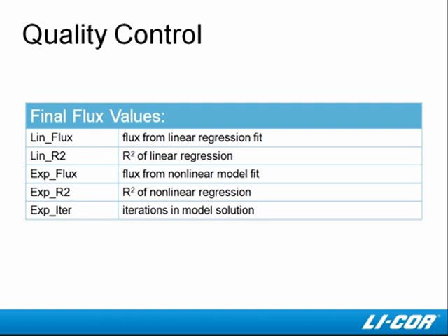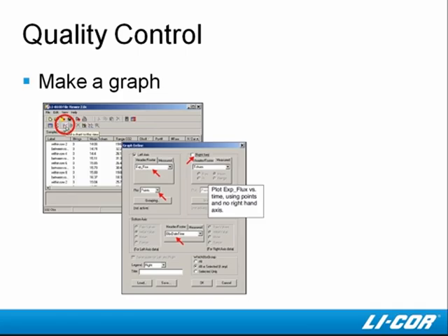In step 3, we set up charts so that you can observe the results of screening outlier data. Briefly, click the Add Chart button. Choose the variable to be charted and the x-axis. And finally, create a chart group so that you can screen multiple variables in one pass. For more details on setting up charts and chart groups, check out page 13 in the manual.